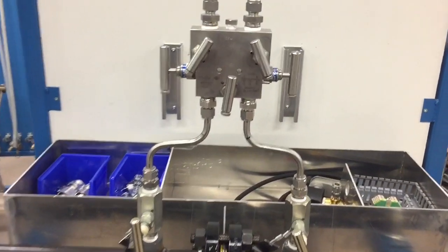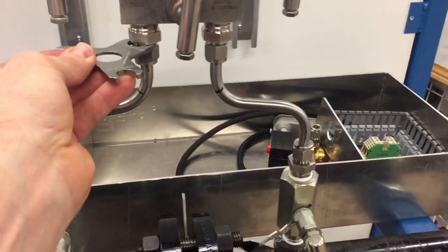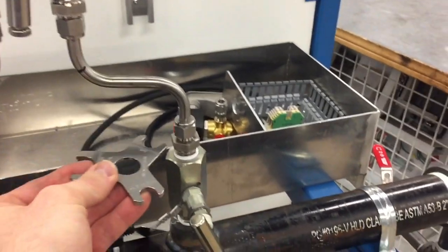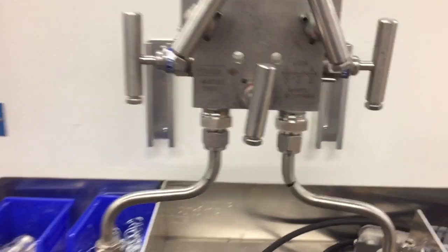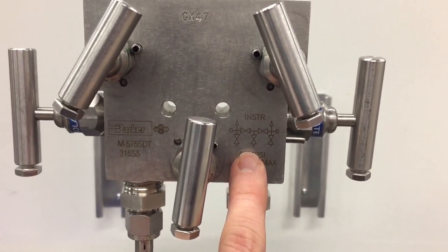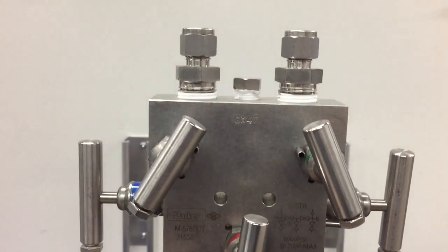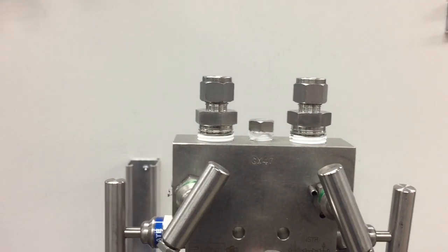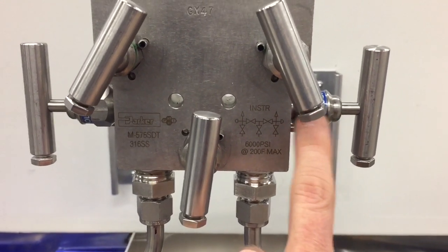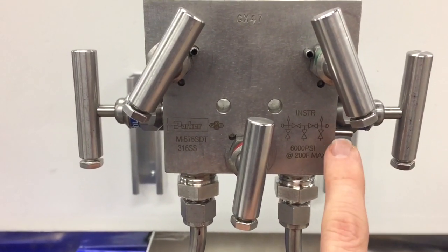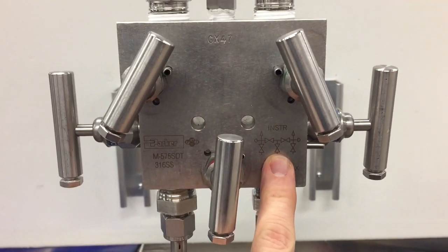So the manifold's installed. I'll just quickly use the no-go gap gauge here and check to make sure that I've tightened all of my fittings. And yes, it won't go into any of those fittings, so they're all tightened. Also important to note the orientation here, just as it was drawn on the piping and instrument diagram. We're going to be coming into the bottom here of the manifold, and then these fittings are the top, and they go out to the gauge. So you can see here, this isolate valve here and here represents this valve right here and right here, and then this valve in the center represents this right here.